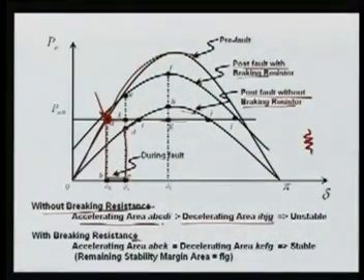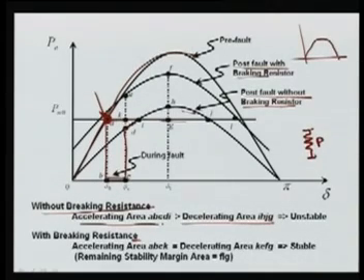It is not X, it is the resistance power that is added here directly, this real power. You must know this is resistance, so only this real power P is added on this curve, which is your P-delta curve. If you add some resistor, this curve will be lifted by the P that is going into the resistor.